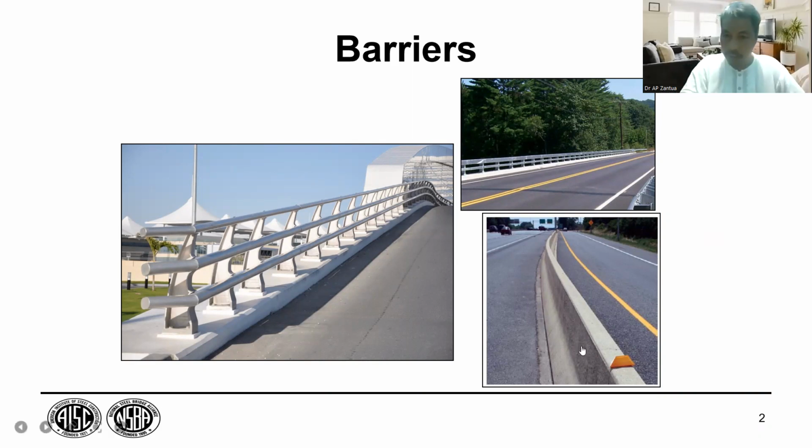So concrete temporary barriers, or movable or portable barriers, are those where I think the length is 1 meter, so you can see a cut every 1 meter. This one is continuous, so it is not portable and not temporary. This is a fixed type of barrier. Okay, so this cannot be moved, compared to the portable or temporary concrete barrier.